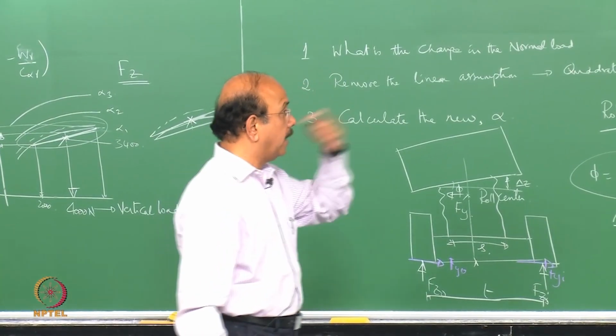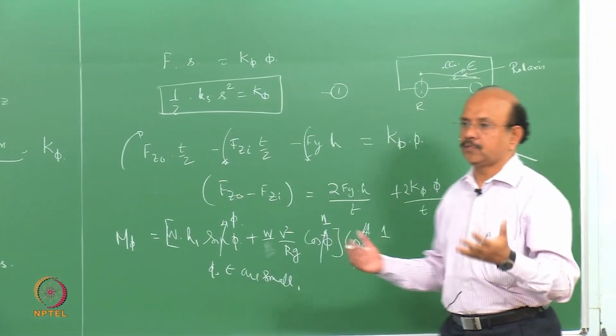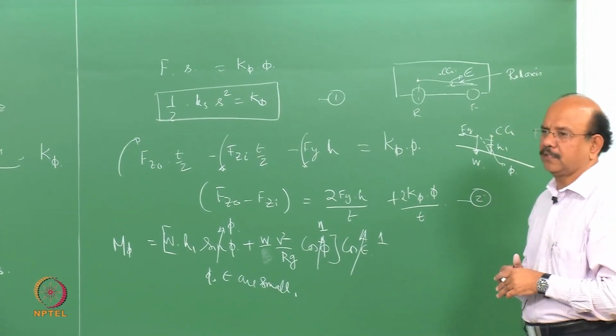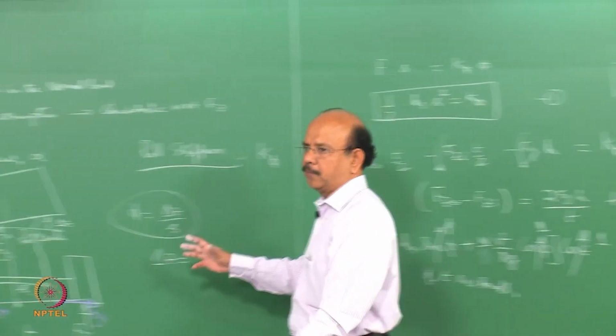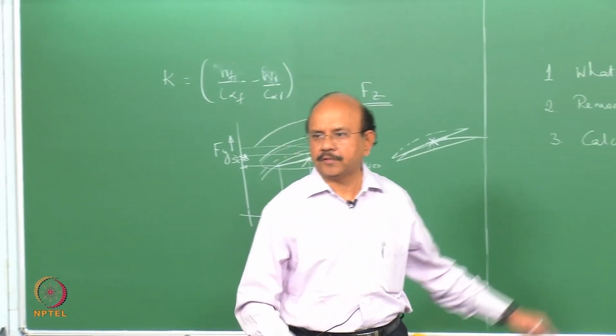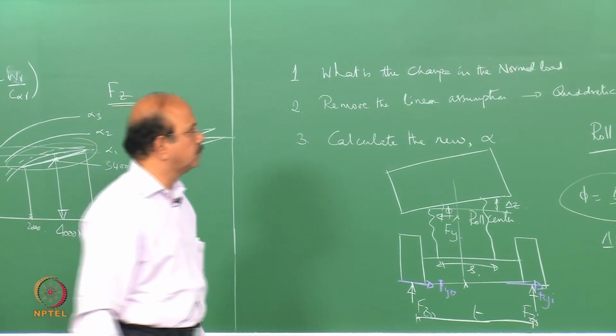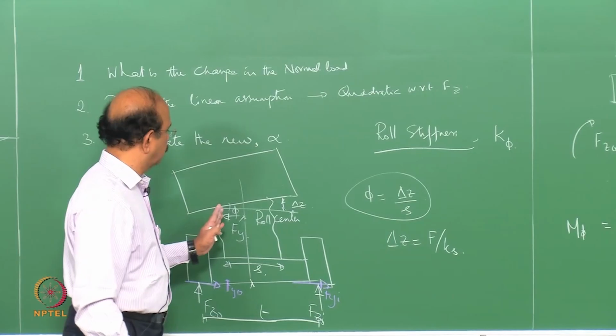Yes? Does the vehicle have just one single roll axis? Yeah. Two roll centers, front roll center and the rear roll center. Front roll center and rear roll center are characteristics of suspension. There's a geometric method of calculating the roll centers that you would have studied in vehicle systems. Center of mass would lie either to the left or the right of the roll axis.